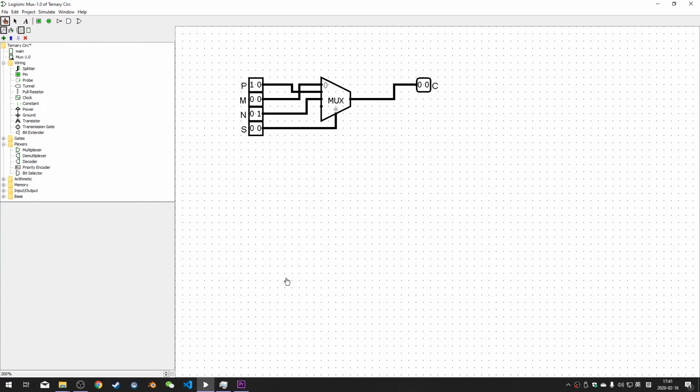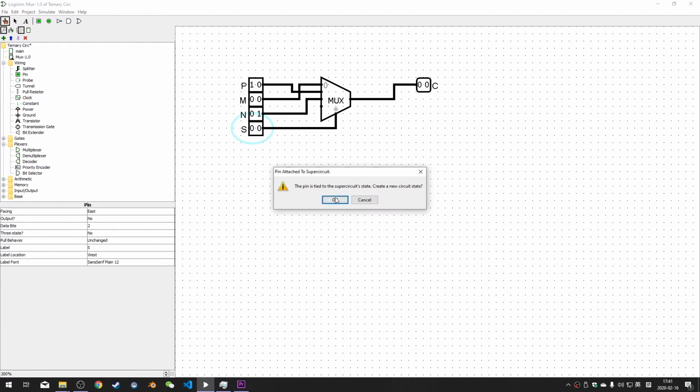And this is the internal of the multiplexer element. I used a regular multiplexer provided by Logisim and left the 4th pin unattached, as we only need 3 inputs. So when we set S to be all ones, the output will generate an error, which is pretty convenient for debugging later on.